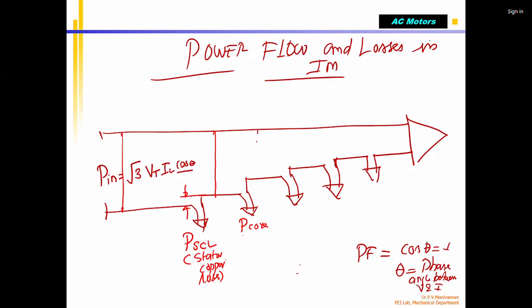After that, you can see that now the input power is this much and it has reduced this much because of the losses. Next one is PRCL, where RCL means rotor copper loss. Okay, then you can see that again it is diminished. Power is gone, reduced. Some amount of power is wasted. Next important is P frictional losses, bearing losses, or all those things. Correct? The rotor is rotating, with the support of bearings, and any other frictional losses. Then because of that the power is still reduced.